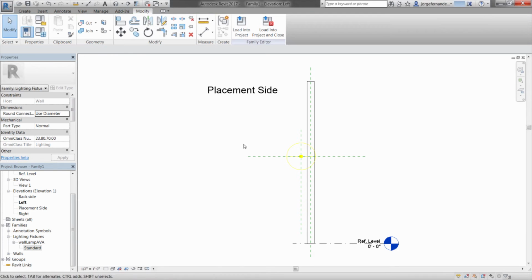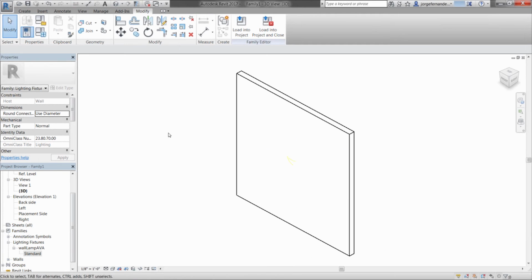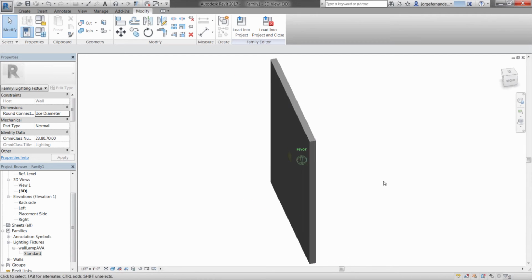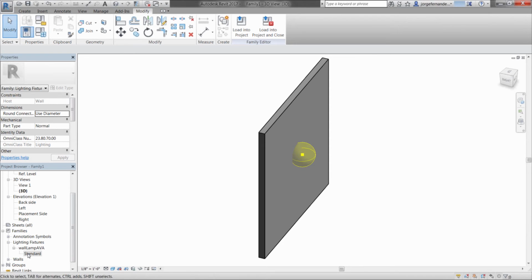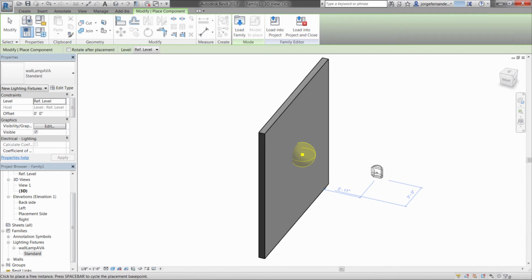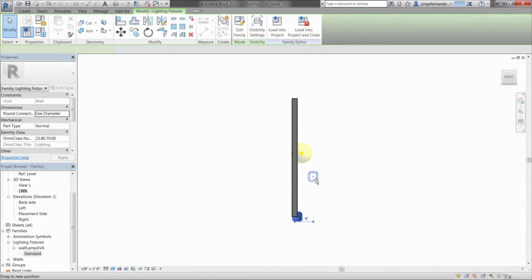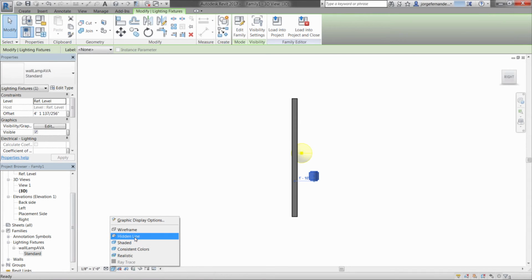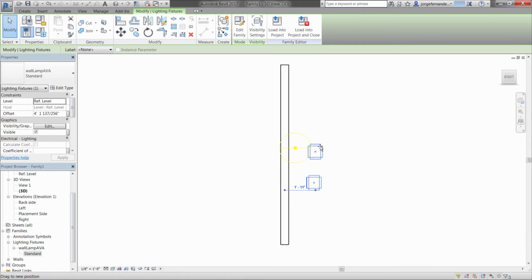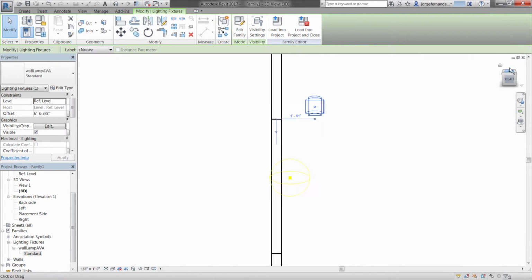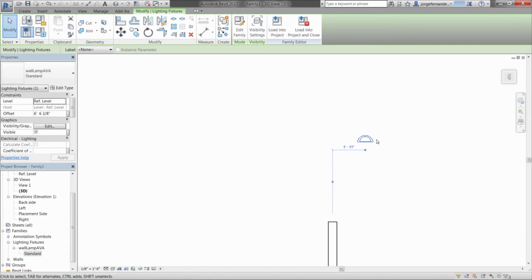Let's do a little 3D view so we can see it better. And we'll shade this here. Makes it a little bit easier too. Let's do that one more time. There it is. Now the way I do this, there are different methods of course, but I like to go over here to my top view and maybe right view and so forth to get it into the right place. In some cases I might toggle back and forth between shaded and wireframe, for example. I'm going to go to wireframe in this case again, and you'll see that I can simply move this up like so. I can move to my different views and start to place it where it needs to go.